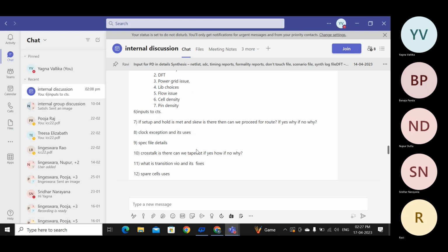See, basically, don't touch net and all is for what you have already built. And clock stop pin, you have to give the pin from which that branch, beyond which it will not build any clock tree. Don't touch net is for when you have built some custom clock tree and you don't want that to be touched. Then you will say don't touch. You understand? So you want some special requirements, like you have added shielding on some branch, so this clock tree is custom built. Then you say don't touch, and it will not touch that clock tree. Okay, that's the point.